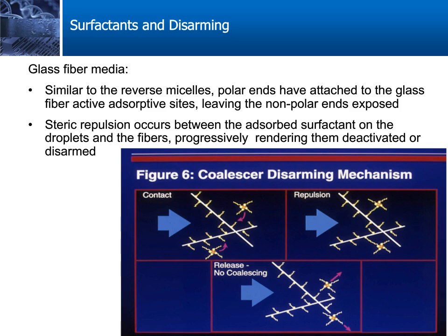This can occur after days, weeks, or months in service, depending on the volume and activity of the surfactants. But basically, you progressively deactivate or disarm the medium so that it can no longer effectively remove free water from the flow stream.